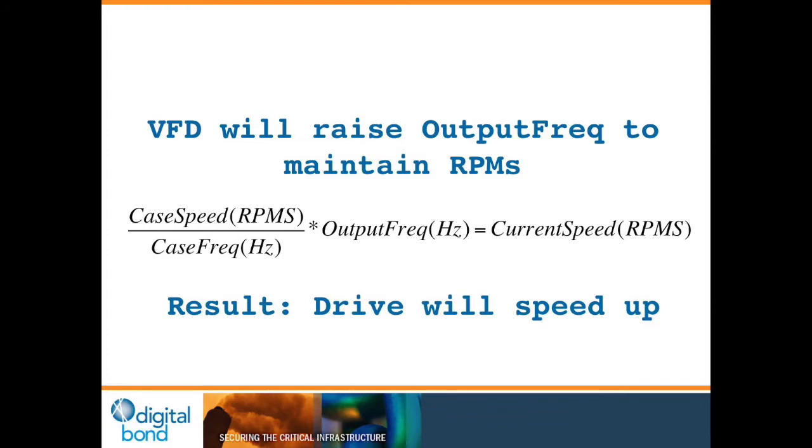So you can kind of trick operators into thinking that they're running their motor at the right speed just by changing these settings. And the question becomes then, is anybody logging these settings? Because it's normally something that you set once in a frequency drive and never change. So are you storing this in your historian data? Or are you logging it somewhere? If it changes, will you notice, is the question.